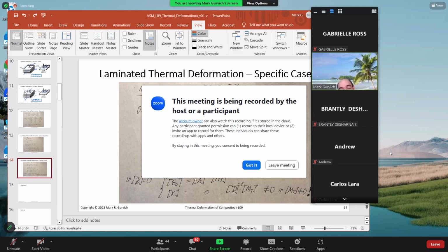You just divide it by delta T, and on the left side, instead of epsilon sub-zero, you will have all the alphas: alpha in orientation XX and orientation YY, and also shear, if any, XY, for the laminated package.